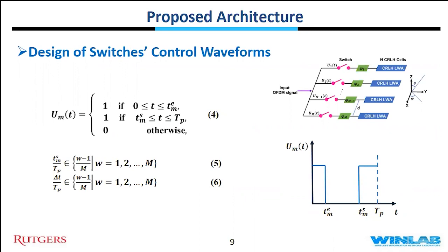So by considering the far-field radiation pattern that we wrote, and the objective we want, to preserve the signal in a specific direction, which is actually the main beam direction of the transmitter, and distorting it in other angles, we found that if we meet equation 5 and 6 for the unit cell control voltages, which we consider as a periodic square waveform, then we can achieve our goal, which is directional modulation. What is important here is when each switch gets on and off in each period, and also the on-time period of switches should meet these two equations, 5 and 6.